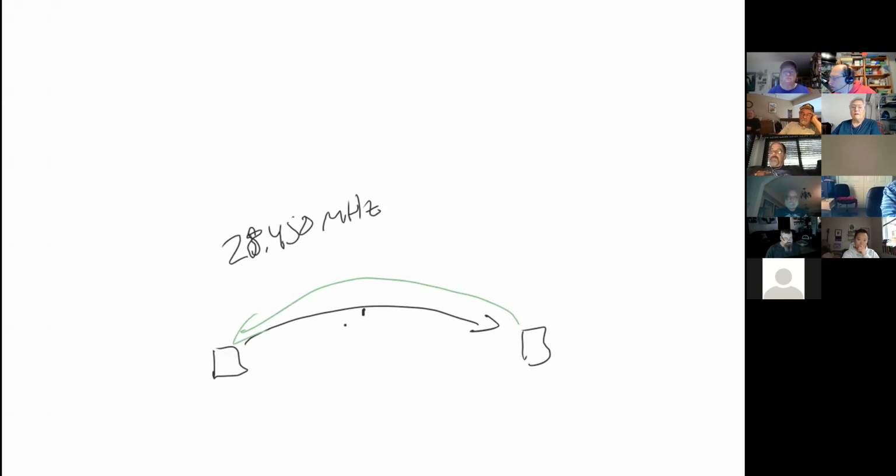And if somebody else is listening to both of them, they will hear the sounds of both of them, which gets a little confusing, at least on amplitude modulation modes such as single sideband. If these are FM modes, frequency modulation, these 2 signals will completely cancel each other, and this is known as a double. What happens on FM is that nobody wins and you hear nothing. You just hear a lot of static, or squealing or screeching or some other horrible sound. So when someone says, we have to work to eliminate doubling on our repeater, that's exactly what that means.